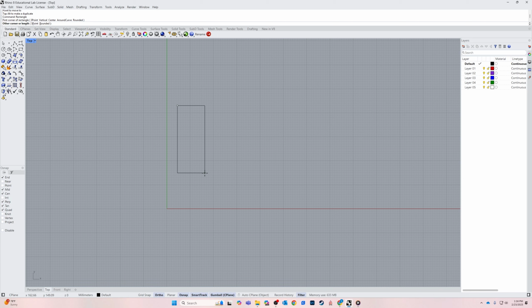But this one I'm going to make a little bit bigger because this is the one I'm actually going to fabricate. And you can pick the size of these that you want based off of how big you want them to be when you fabricate them. I want this to be about 18 inches by 18 inches. So I'm going to do 9 inches, enter, by 9 inches, enter. Okay. So this square here is 9 by 9, and when we're done, it's going to almost be 18 inches. I think it's going to be a little bit less, but I'm fine with that.